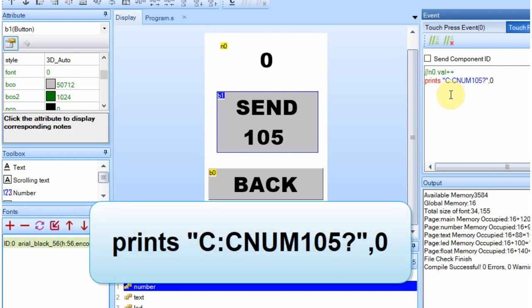But if you're not going to use the library, the Arduino is going to have to know the command that you sent it. So every command that I send to it, I start with C:C. In other words, I use the cheap controls with a colon in between. When the Arduino sees a 3-character string, C:C, it knows that that's the beginning of a command. Then I use a 3-character string to denote the command. In this case, I'm using NUM for number. So I'm sending C:C NUM, and that tells it that it's getting a command and that the command name is NUM.